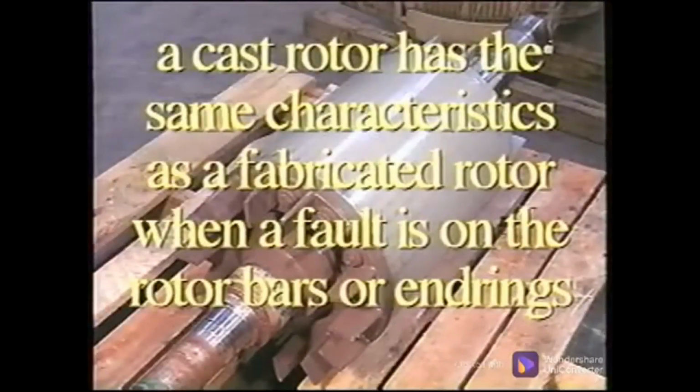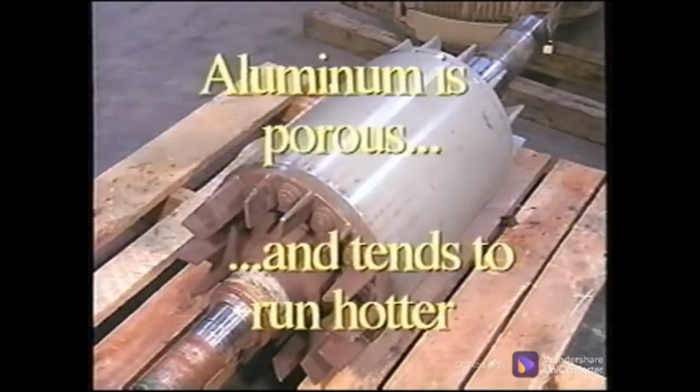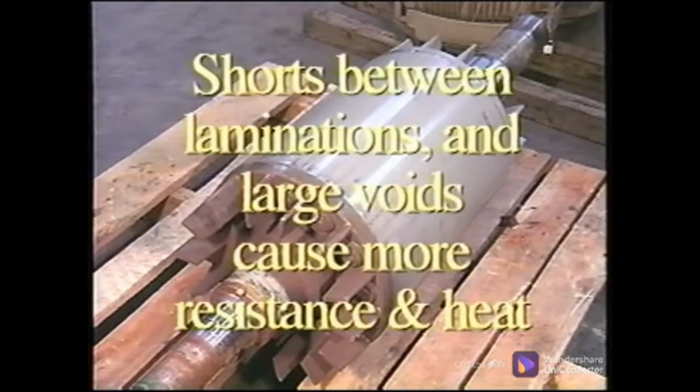A cast rotor has the same characteristics as a fabricated rotor when a fault is present on either the rotor bars or the end rings. However, aluminum is a porous material, meaning that it has minute voids throughout, causing it to have higher resistance and run hotter. Shorts between laminations and large voids also cause more resistance and increase heat.